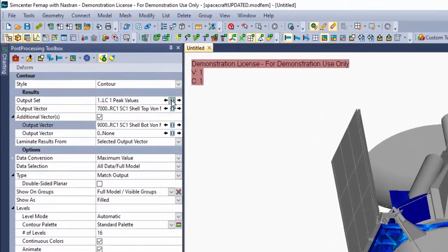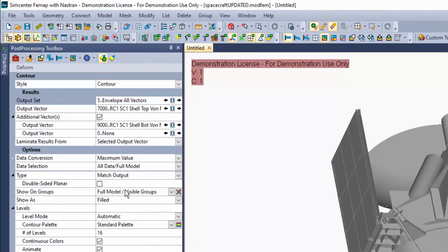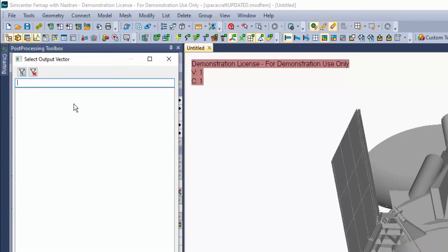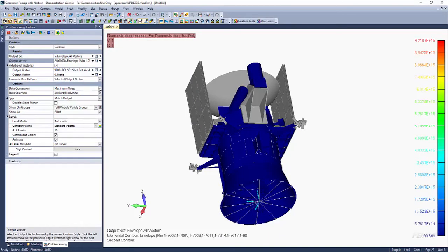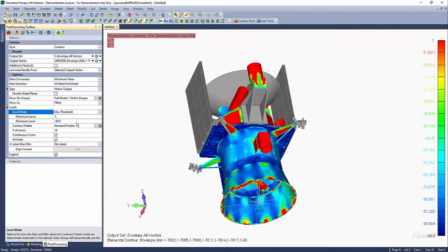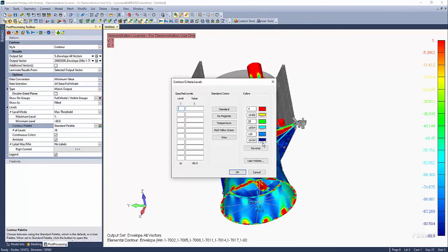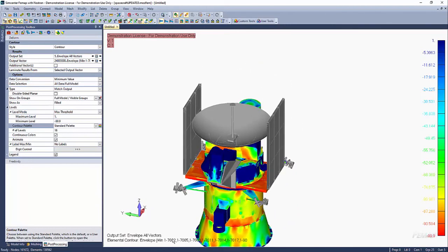To assess the stress magnitude, it's also convenient to look at the margin of safety results. There are results for each of the stress cases we created and which we enveloped using the FEMAP tools. Load the peak margin of safety. And let's invert the colors such that the smaller margins are red. And let's specify an overflow value. You can see that the minimum margins of safety are negative, which means that the stresses are much too high in many regions. These confirm that the input function notching wasn't successful.